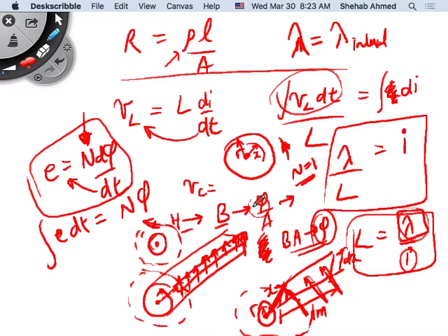But in the case where you're looking at internal flux linkage, it's only linking a portion of the conductor, from the core of the conductor up to a point x away, not the full radius. This portion is defined by the ratio of the small area to the big area, the full conductor. So you're not linking 1; d lambda is not equal to d phi anymore. d lambda is equal to a portion of d phi, so k times d phi.